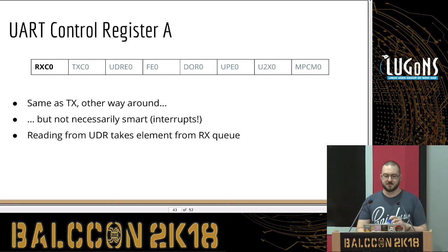So what about reading? Reading is basically the other way around, except we won't have the data register empty flag, because now the data register has to have some value, and we can just read from the data register.